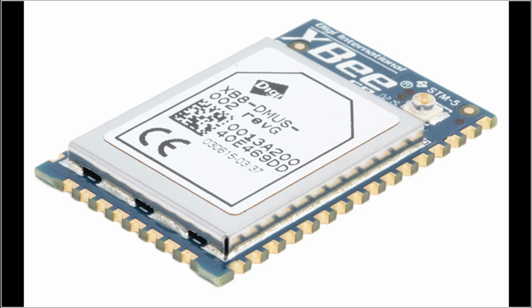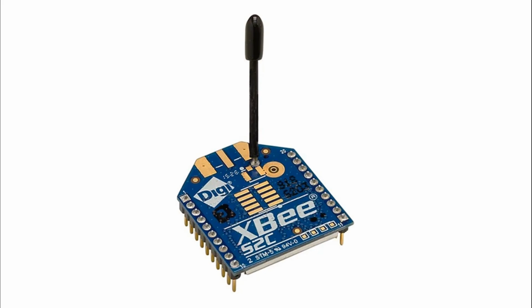Flexible device roles. Supports various roles for devices. Coordinator, one per network, responsible for starting and managing the network. Router, for routing data across nodes and expanding network range. End device, communicates only with its parent router or coordinator, helping conserve power. Range, typical indoor range up to 100 meters, 328 feet, and outdoor range up to 300 meters, 984 feet. Extended range possible through mesh networking, where nodes act as relays.